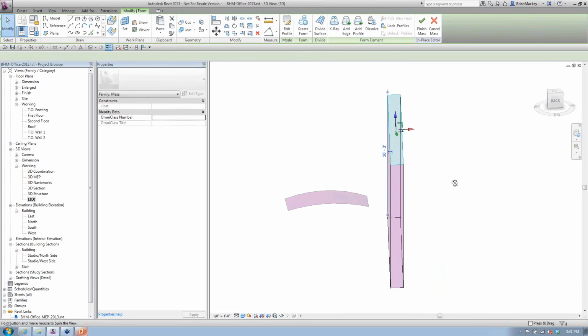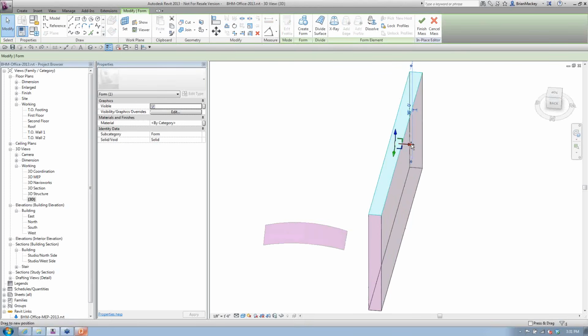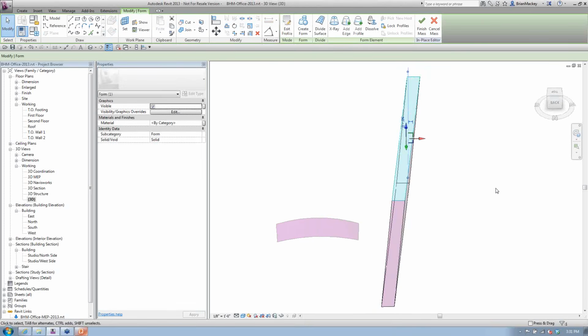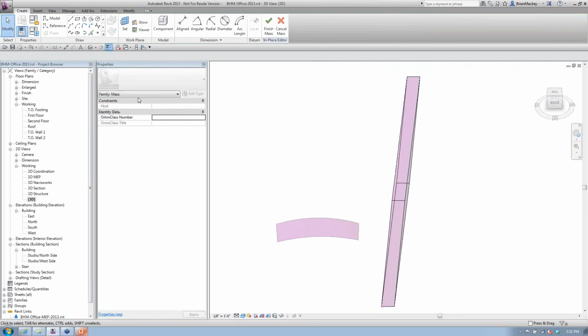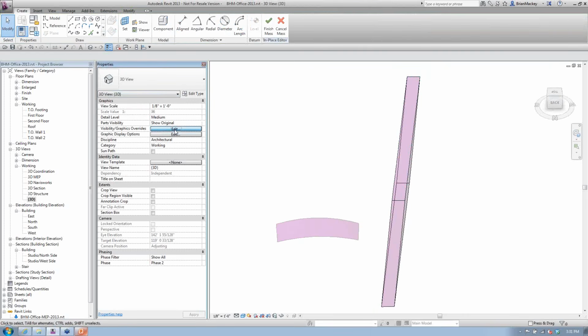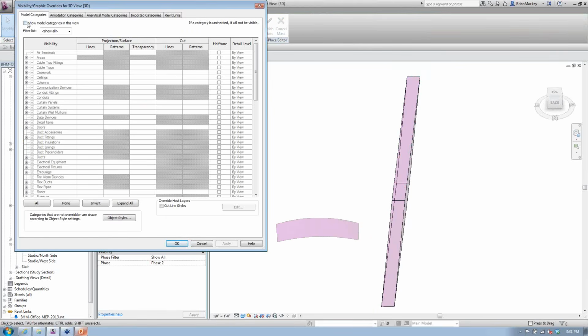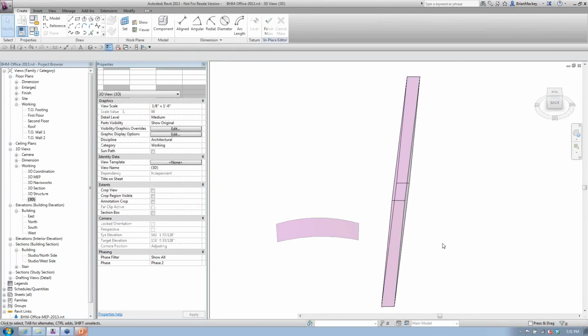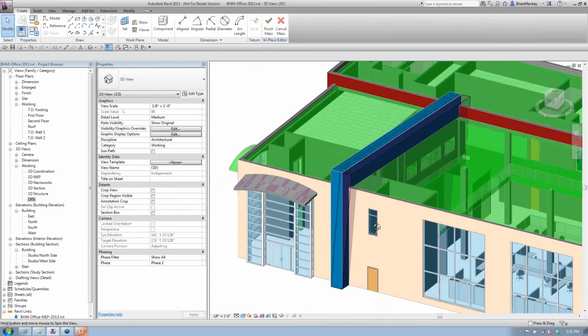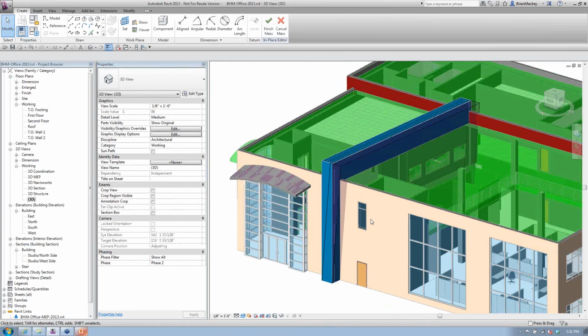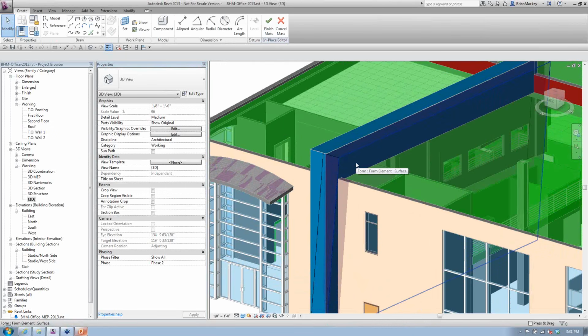In my case, I really want to take the whole thing and move it over. Okay? So now that I've got that done, that's all fine and dandy, but if I create this mass just the way it is, it's going to create walls through the entire inside of my project. And maybe that's great, but I really just want to create some walls that are going to be dealing with notching around the existing surface.